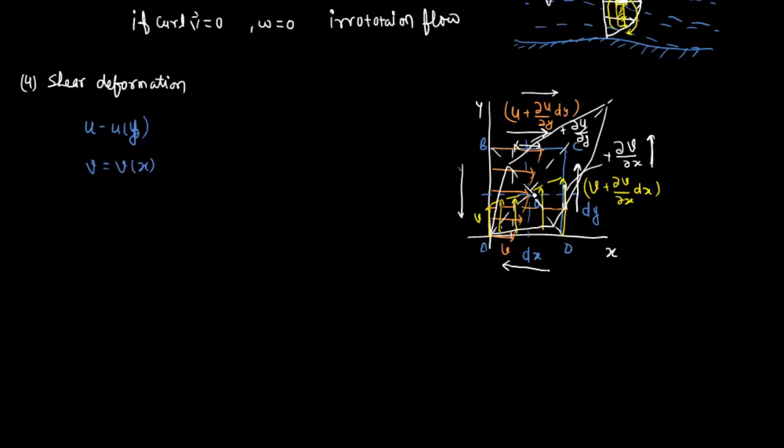Okay, so this deformation is in the shear plane, sorry, that is in the 2D plane. So we can define that as shear deformation in the xy plane. Again we are taking the average value. So in this case both are positive, so I am simply adding them, that is 1/2 of ∂u/∂y plus ∂v/∂x. So this is the deformation in the xy plane.